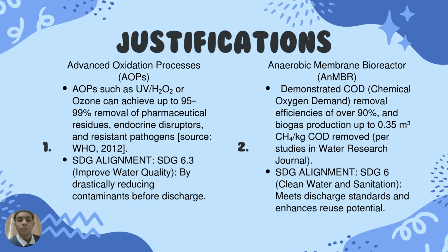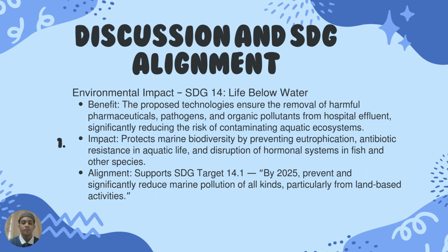Secondly, for anaerobic membrane bioreactor, it demonstrates COD, chemical oxygen demand, removal efficiencies of over 90% and biogas production up to 0.35 cubic meters per kilogram COD removed. For the SDG alignment, SDG 6, clean water and sanitation. It meets discharge standards and enhances reuse potential.